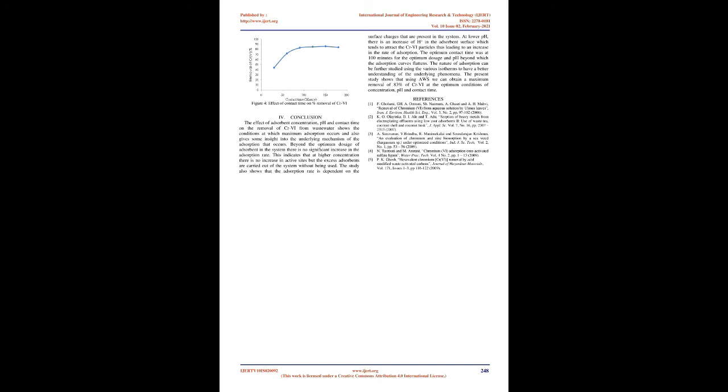C. Effect of contact time. The time required to reach equilibrium for adsorption by AWs is shown in figure 4. The adsorption of chromium was dependent on pH of aqueous solution and increased with decrease in pH of Cr6. The contact time was varied between 30 minutes to 150 minutes. The rate of adsorption increased at lower contact time and then it reached equilibrium at 100 minutes of contact time. At this condition the maximum removal of Cr6 was observed at 83% for a dosage of 2.5 gm per 100 ml stock solution at pH 2.